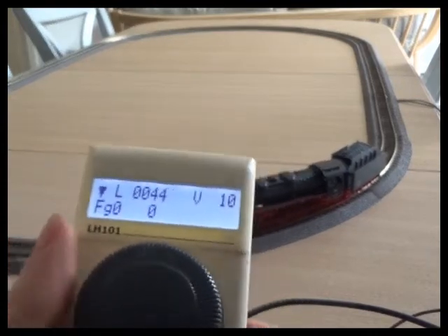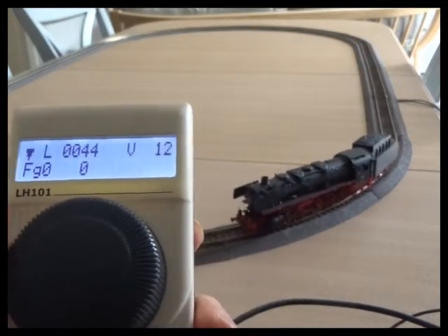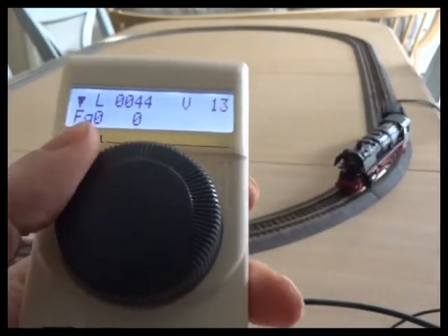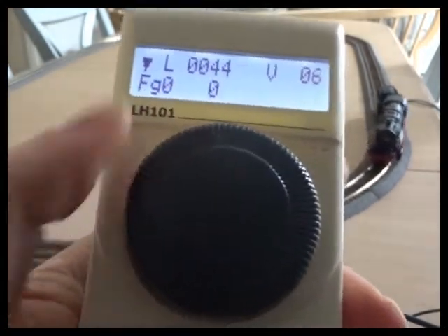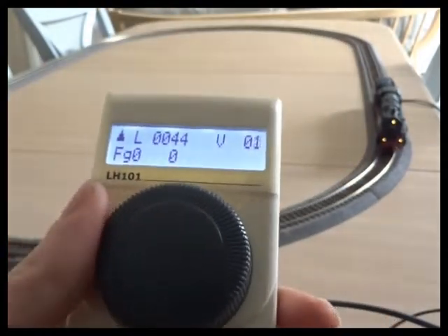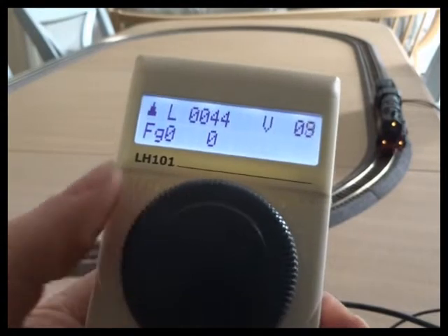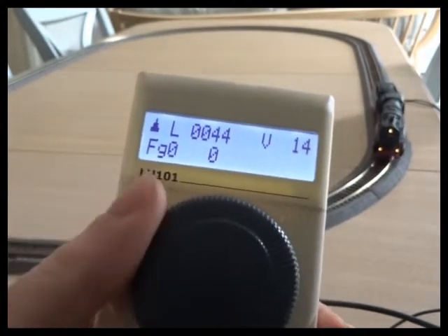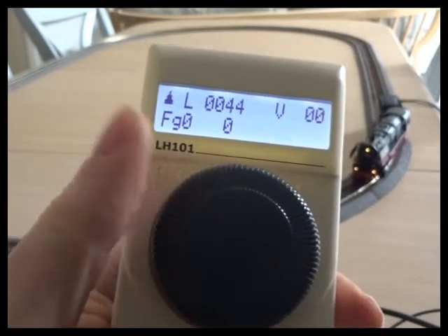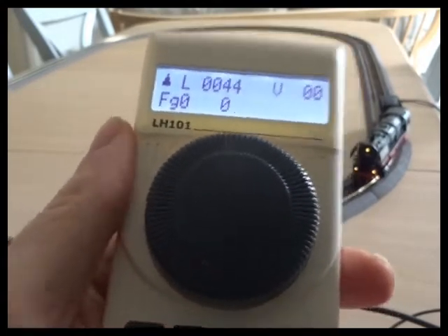Very occasionally we run across locomotives that have got settings of 14 or 27 speed steps. 27 is from people that have used Fleischmann systems in the past, so the Lokmaus and the Twin-Center defaulted to 27 speed steps. So in CV29 you would correct that by using bit 2.